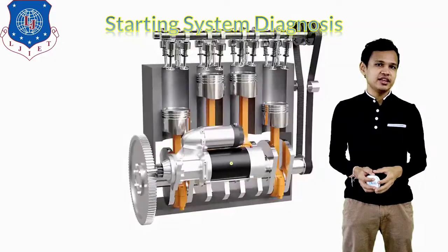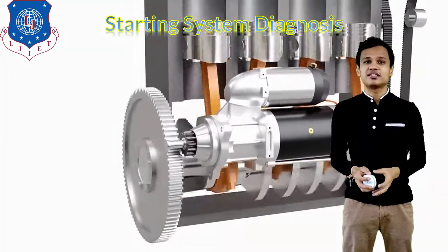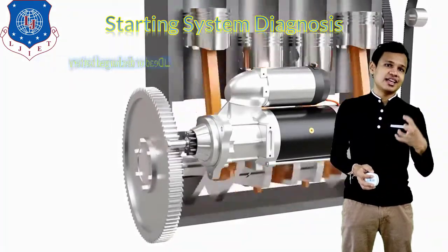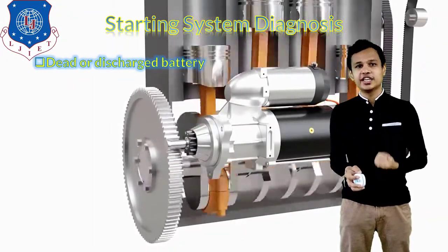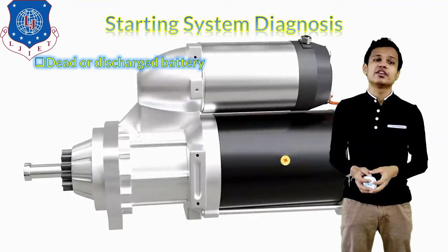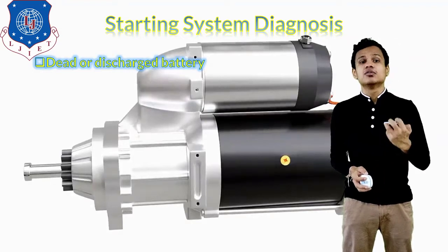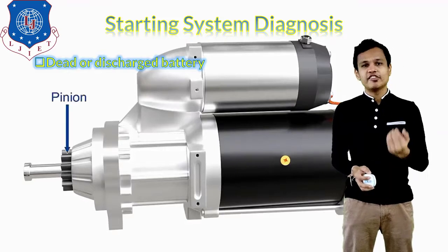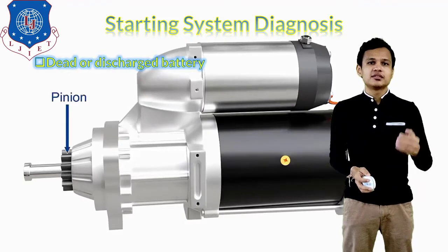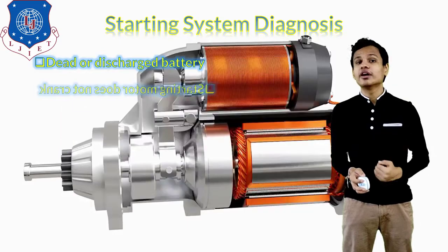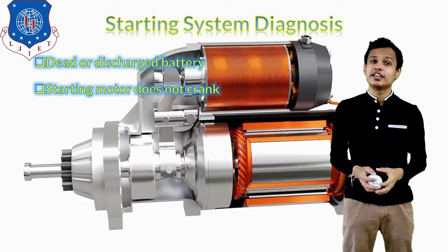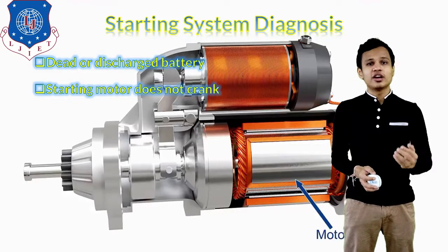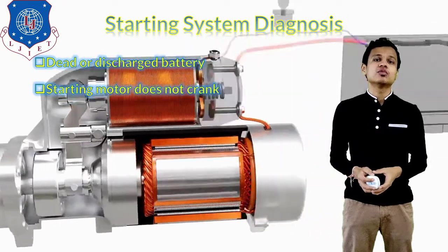Next thing is the starting system diagnosis. In the case of starting system diagnosis, there are some problems associated with the starting system of the vehicle. First, if the battery is dead or in the discharged condition, then the vehicle will not start. Second, if the starting motor is not cranking our vehicle, then also the engine will not start. For that, there will be a problem in the starter motor.